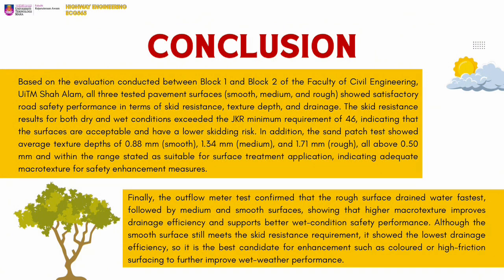In addition, the sand patch test shows average texture depth of 0.88 mm for smooth, 1.34 mm for medium, and 1.71 mm for rough, all above 0.5 mm and within the range stated as suitable for surface treatment application, indicating adequate microstructure for safety enhancement measures.